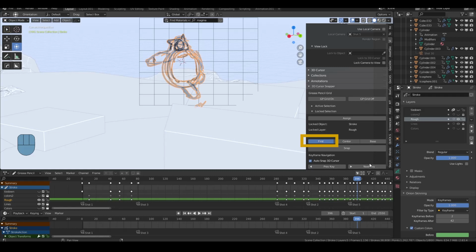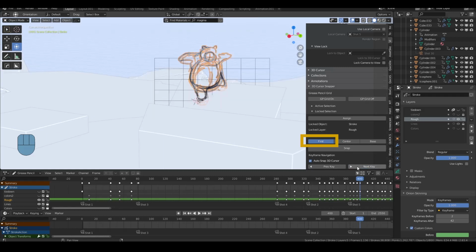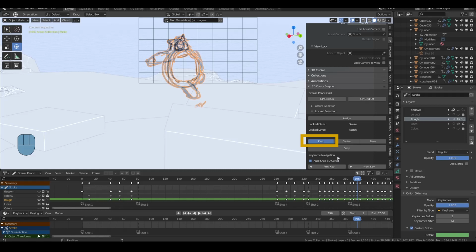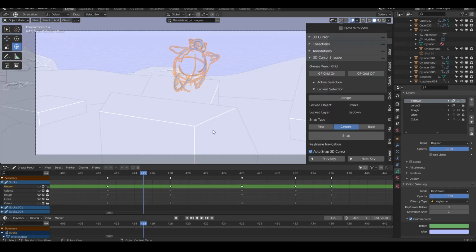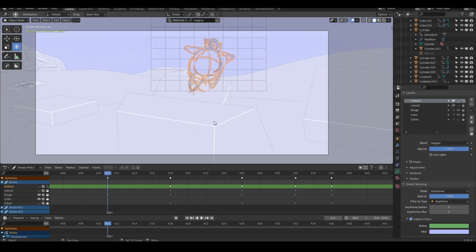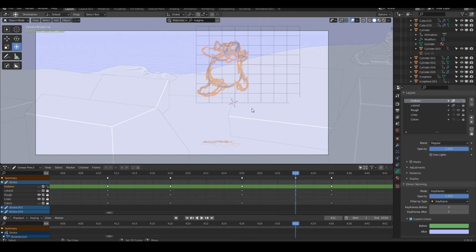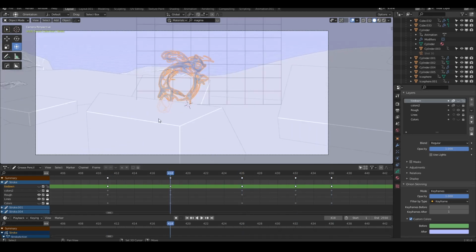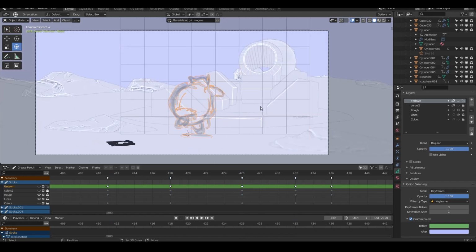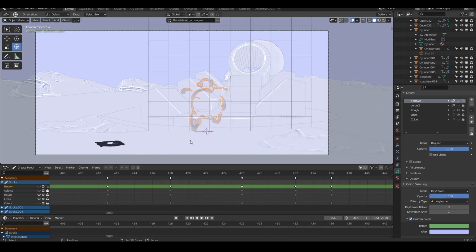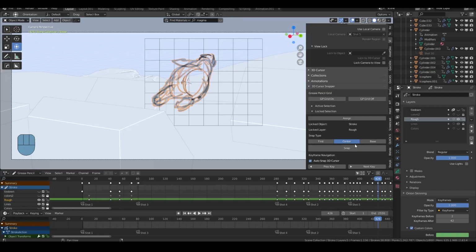Now it does that in one of three ways. The first is, if I select first and do it, you'll see that it pops to the point where you first drew a stroke. Personally, I like center because it centers everything around roughly the mass of the vertices that are there. And then the final setting is base. What that will do is step to the bottom. Can you see there? It'll always choose the lowest vertex of the artwork. This is particularly useful when you're on the ground, so it's always the lowest point to the ground. So keep it on center, and then you go next.